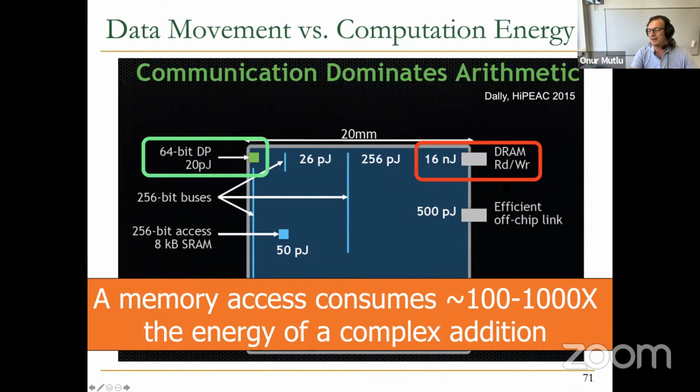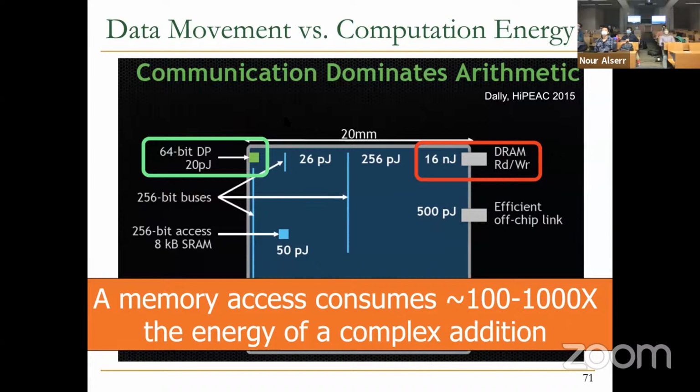So this is very interesting, clearly, to look at. If you are faced with a trade-off like this, then a good question to ask is, does it really make sense to bring data from memory to the processor chip to do a relatively very simple operation? Because we're causing a lot of energy to move the data. And the answer would be not necessarily. Later we will talk about in-memory or near-memory computation, especially if you do not have good locality in your workloads. You cannot exploit the caches extremely well, you cannot overcome this energy disparity between memory access and computation.